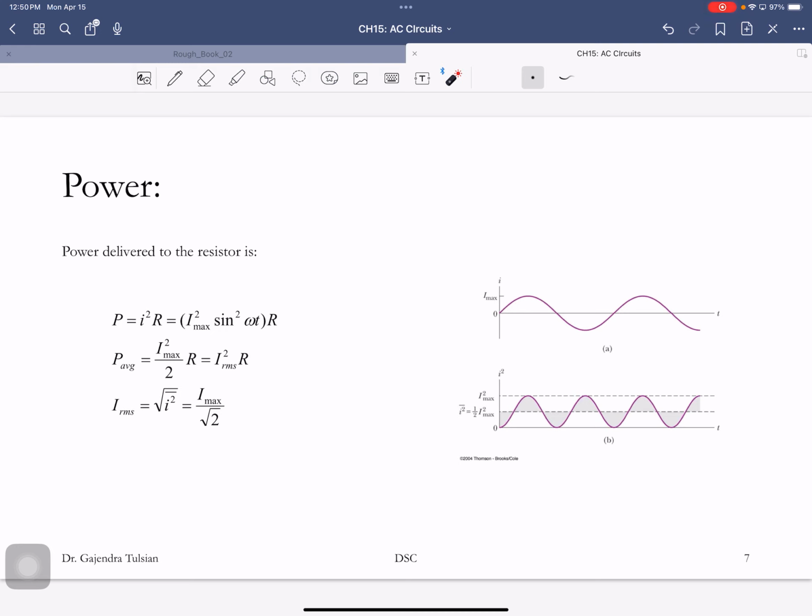Anything that flickers more than 30 times a second, your vision persists. That's how TVs work. On a TV, it's a still image that's being drawn. If they draw it more than 30 times a second, then it appears as continuous smooth motion. But the bulb is flickering 120 times a second. Since your eyes can't perceive that, all we are interested in is the average power.